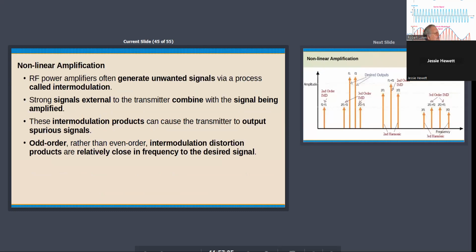I don't think this happens with FETs, but I'm not sure. I don't think it does. Because the effect there is the leakage current from the base to emitter, and that's why the emitter resistor helps limit it. So as that base emitter current due to heating increases, then it increases the collector emitter current, and that's more heat.